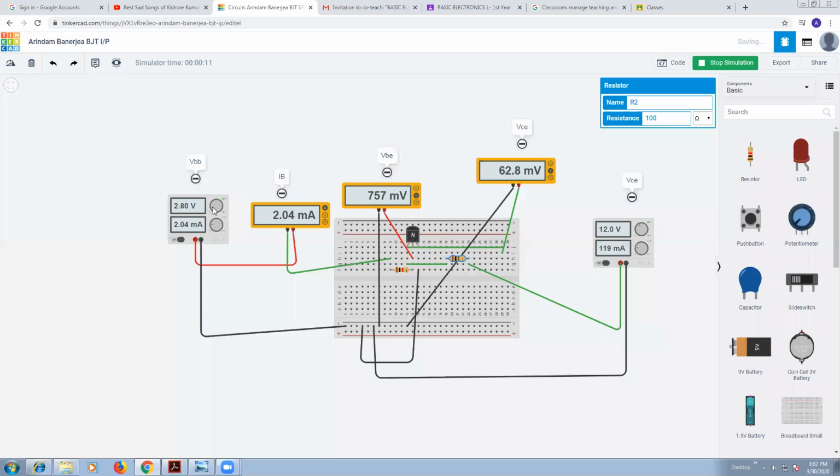Set the voltage here, VBB, 0.0, 0.2. On the left side source, here the power supply will be 0 volt and the current should be set to 1, and then this other power supply we have to keep at 6 volt first.